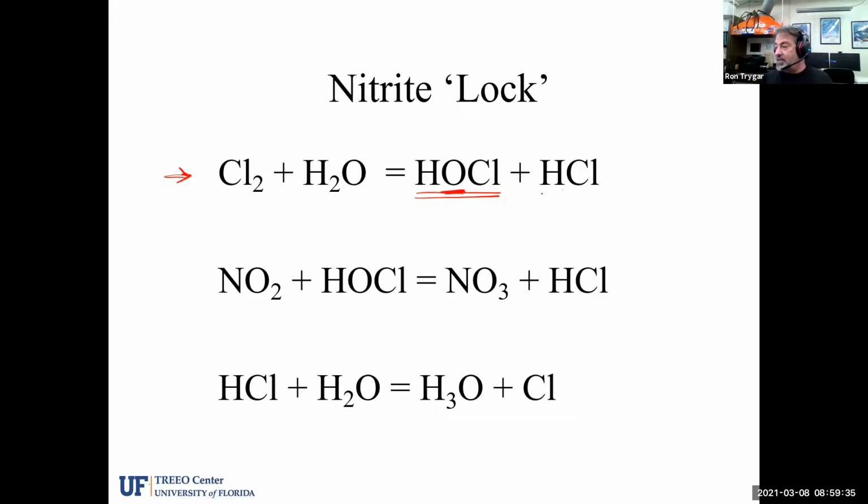The hydrochloric acid is not quite the strong disinfector that we would like it to be. It doesn't have the available free oxygen that comes apart. Hydrochloric acid is generally ionized as well, so it presents a bit of a disadvantage when trying to break through the negatively charged bacteria, cells, enzymes, and slimes around the pathogens. So the hydrochloric acid is not quite as effective as a disinfectant as the HOCl is. And by the way, at certain temperatures and pHs, we can see a dissociation of hypochlorous acid into another form.